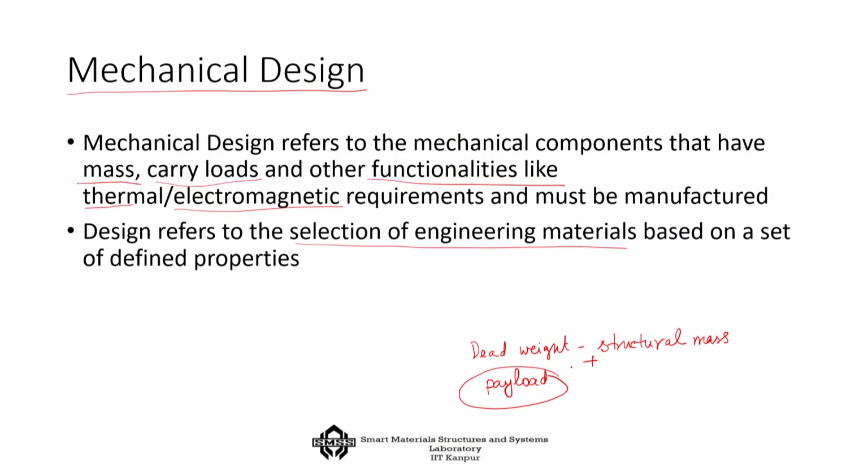As I told you that generally these sorts of things are packaged in a long stack. So, the weight of the stack also comes on the system. So, what should be that stack size? That will be an additional force in addition to the payload that it is going to carry. So, dead weight which is having structural mass plus payload, and then we have to think of the environmental condition which is going to give me additional forces, okay, that can give me the additional forces. And based on all these things, the embodiment has to happen.